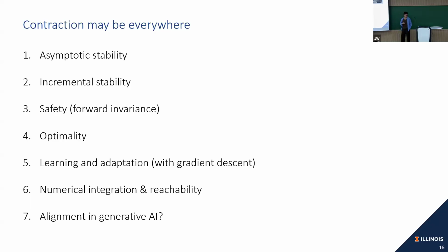And the safety, which is, if you know barrier function, which is known to be a dual of a Lyapunov function. And what it basically does is that you try to converge your system to a safe set, so that your safe set is going to be forward invariant.